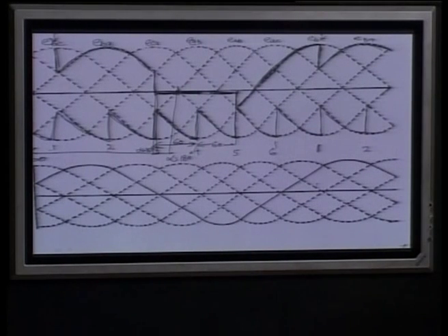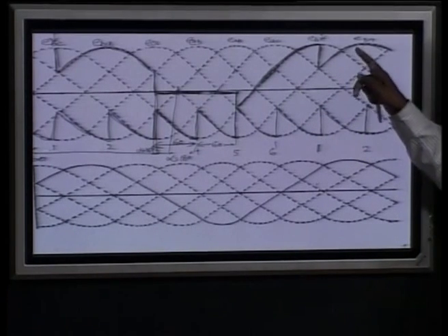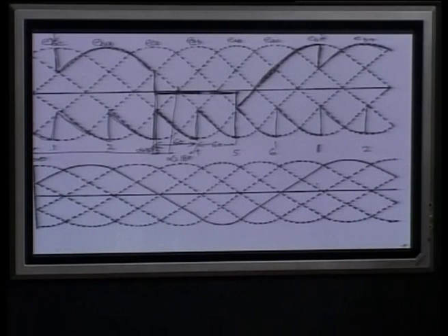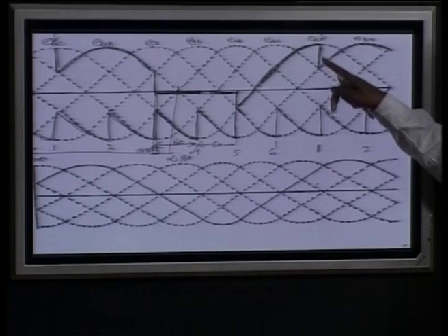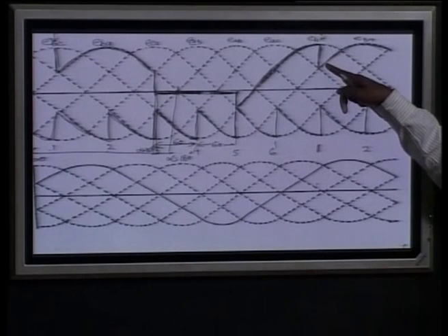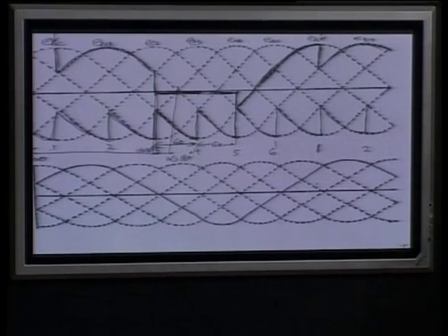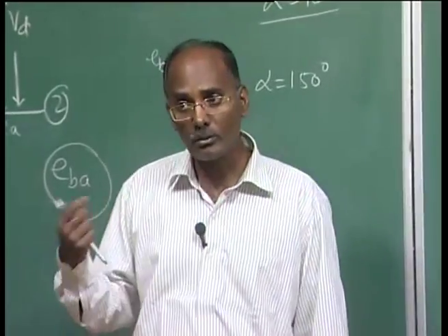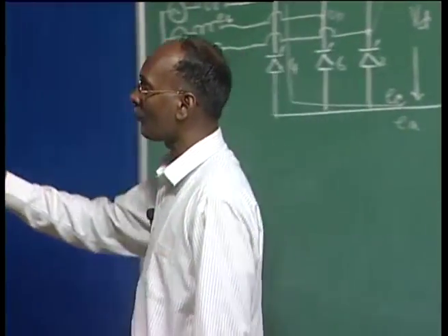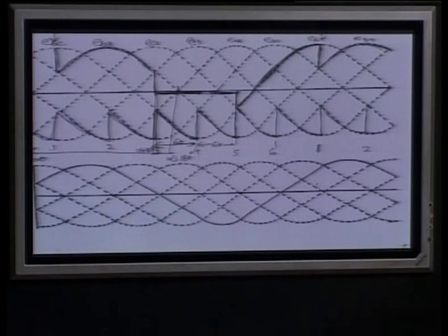And that's why in inverter operation this is a big deal, because whenever there is any spurious signal, the valve may conduct, even though there is a huge dV by dt. There may also be certain jumps in the voltage and certain jumps in the current that may lead to misfiring of this valve, and that is called commutation failure, or there are other problems. So, that is why inverter operation is very risky and is very cautiously maintained.